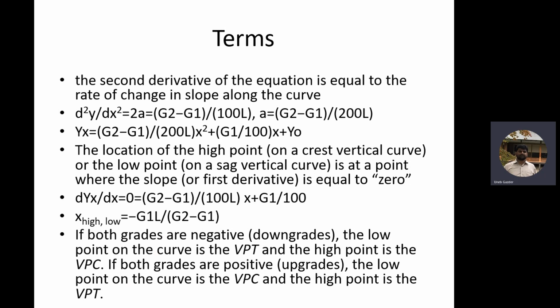Another thing you can do to check your calculations: you calculated VPT, right? We can calculate VPT using the equation as well. How? You put x as 600. x equals the length. You already calculated VPT, so this equation can give you a check. Clear? Any questions?